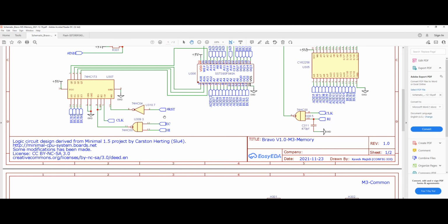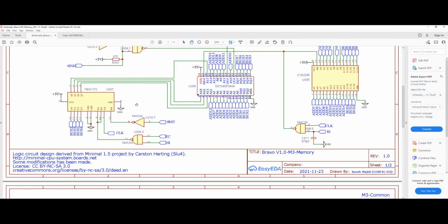Now, this combination of EC and HI is quite unique, meaning that in no other operation in this computer do we have both of those signals high at the same time, right? So if it's unique here, that means that whenever we want to control the bank, we could just bring those high, and therefore control our register. All right, so hopefully everything is clear so far.